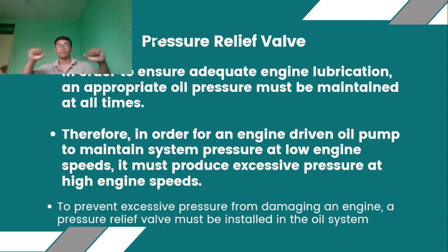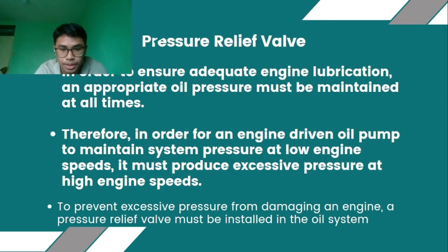nagme-maintain ng ating pressure. So, in order to ensure adequate engine lubrication, an appropriate oil pressure must be maintained at all times. Therefore, in order for an engine-driven oil pump to maintain system pressure at the low engine speeds, it must produce excessive pressure at the high engine speeds.